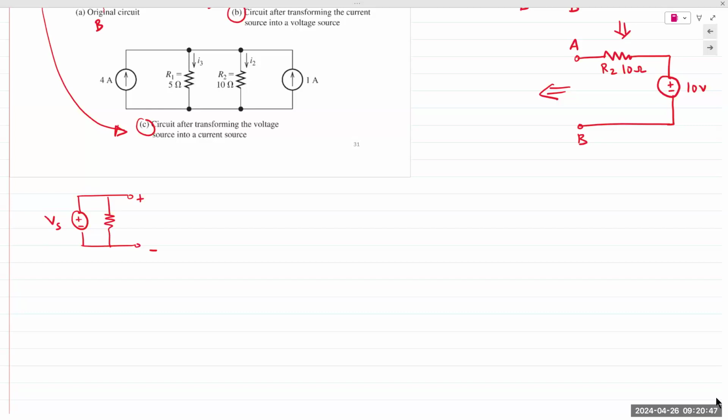So we define that internal resistance of the voltage source as being in series with that voltage source. If we represent it as in parallel, we cannot accurately describe a voltage source at all, because the voltage source would be in parallel with the resistor. The voltage remains constant across the resistor, and then it would not describe that voltage source accurately. Does that answer your question? Yes, it does. Thank you.